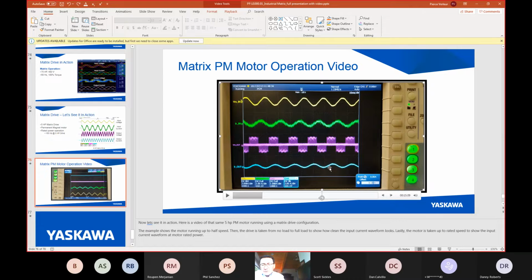Significant lead length, significant problems, significant cost advantage to the matrix. And we've talked pretty much about the conventional diode front-end drives. You know from previous discussions in this class that the active front-end drives have a much better performance because there are two inverters, one pointed at the motor, one pointed at the line. Let's just in the last few minutes briefly talk about how we compare those situations to a matrix drive.